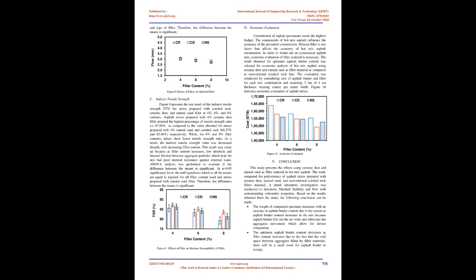As a result, the indirect tensile strength value decreased linearly with increasing filler content. This result may come about because as filler content increases, there is low interlock and internal friction between aggregate particles, which leads the mix to have poor internal resistance against external loads.